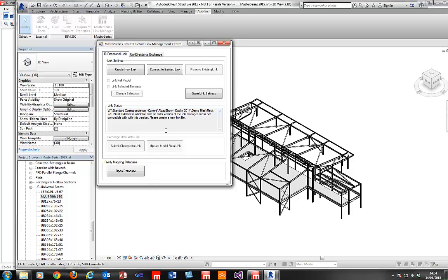Previously, our mapping used two technologies, where we had library type sections, i.e. steel sections that are part of a steel sections library, those mapped entirely based on their name. So for instance, we would have taken this 457191 and been able to find the equivalent name in MasterSeries. Problems then started to arise where a user might turn around and say, well, I've renamed this section to MyUB or Fred or some other summarized name. That made it incompatible then with what was going on in MasterSeries. And to counteract that, we give you this separate section mapping area where you could map this particular name to a known name in the MasterSeries section library for that, and that was for one instance of a section.